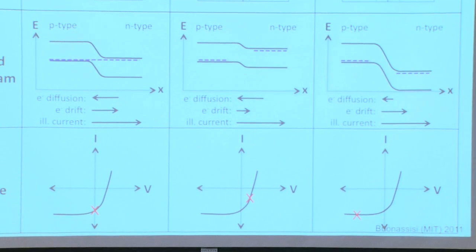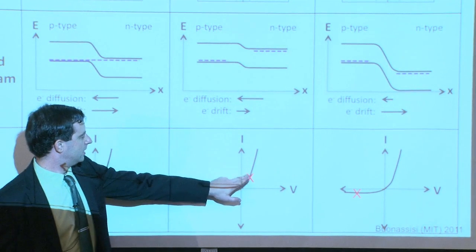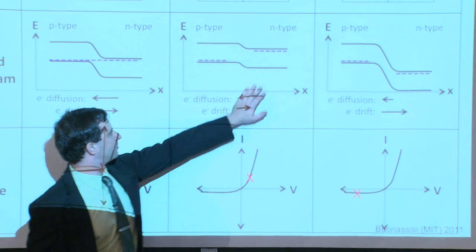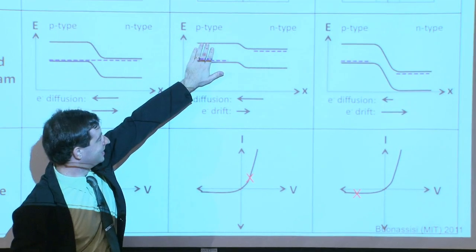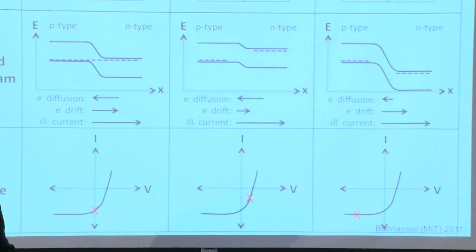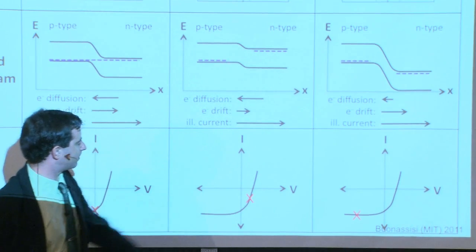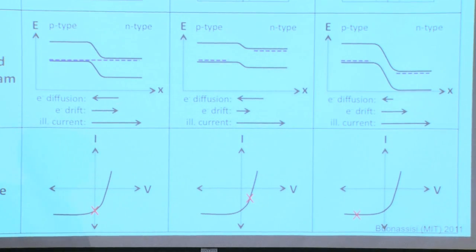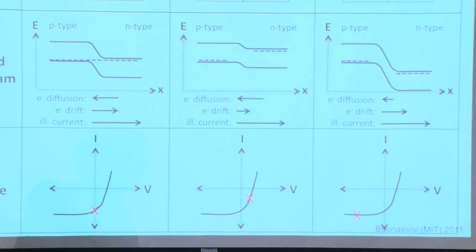That's pretty cool. That wasn't the case when we had the device in the dark. Here, in forward bias conditions, we're actually forcing carriers from the n-type material into the p-type material, right? But under illumination, now we have all of our carriers traveling from the p-type into the n-type. What's varying is the potential that the carriers have, and of course the total amount of current.